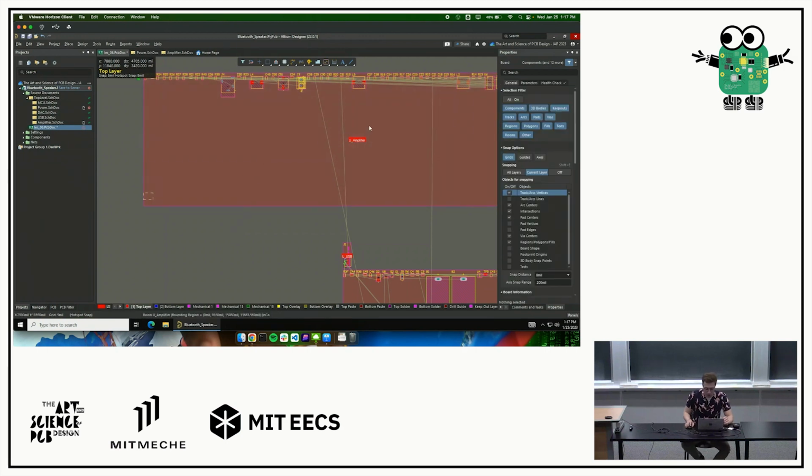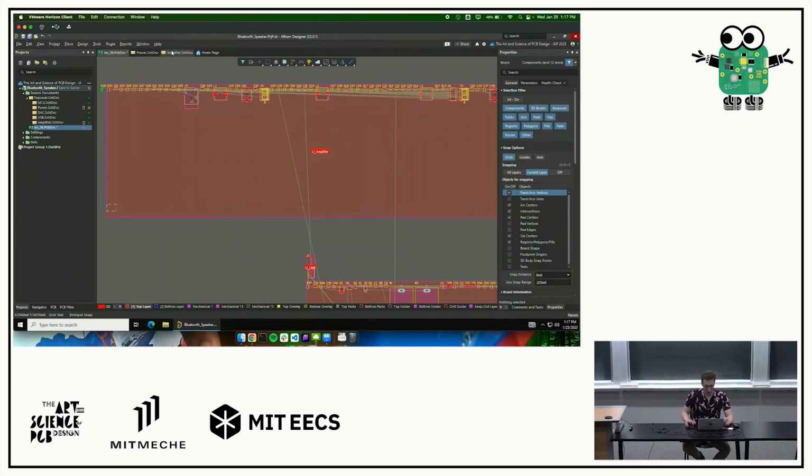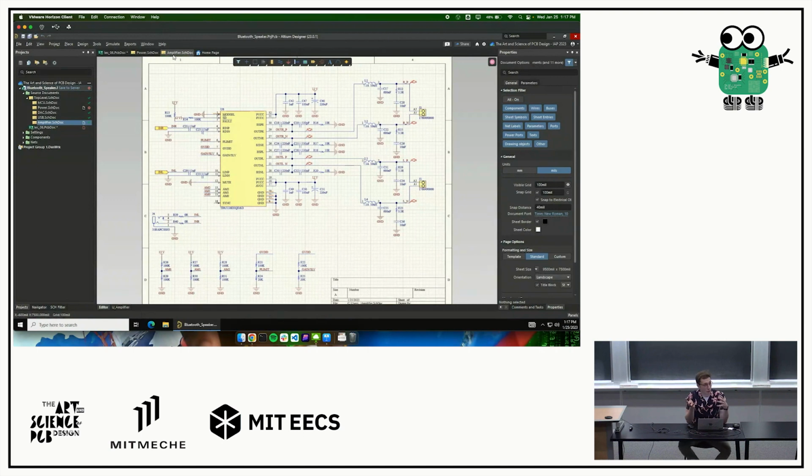Cool. So let's have a look at our amplifier schematic. When we're doing layout, we want components that are electrically connected together to be physically close together, right? Because that means we have to route really short wires between everything. Well, conveniently, we needed to figure out what components are electrically connected to each other when we were making the schematic, right? In order to draw all the lines and stuff. This is a reasonably neat schematic. It's not perfect, but all the stuff is reasonably close together, right?